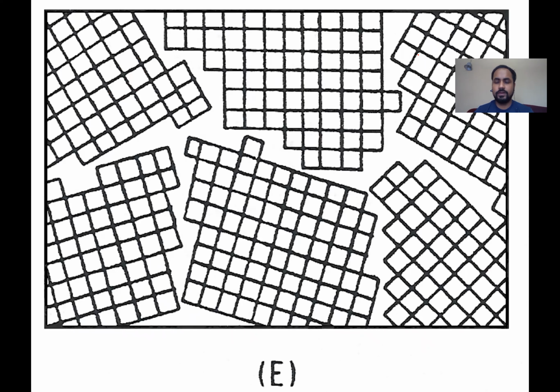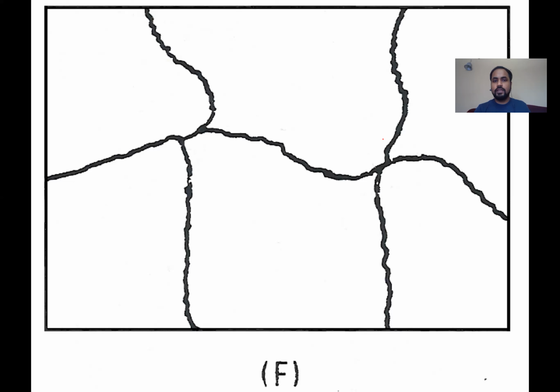As you cool it down further, you'll see it reaches a stage where it cannot go further. It will meet up the next unit cell. And when that happens, that's the region which forms something called the grain boundary. So you get the formation of grain boundaries. Grain boundary basically means if you cross that region, you will have grain of different orientation.